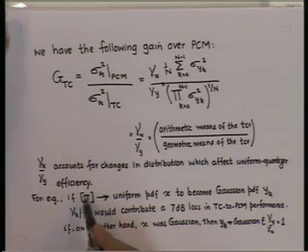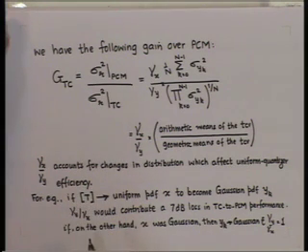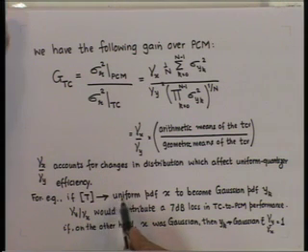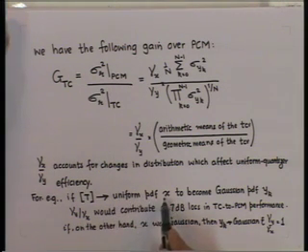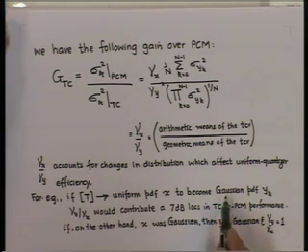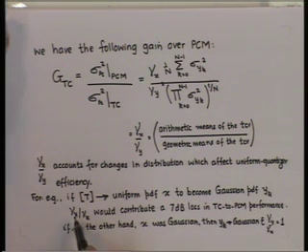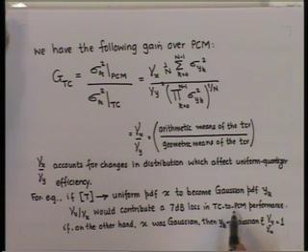For example, if the choice of the transform T converts uniform PDF x to become Gaussian PDF yk, then this factor gamma y by gamma x would contribute a 7 dB loss in transform coding to PCM performance.